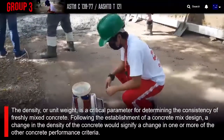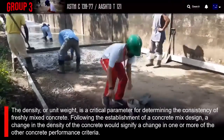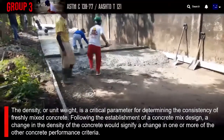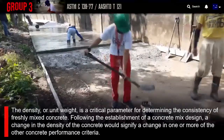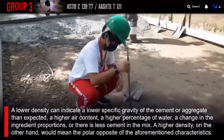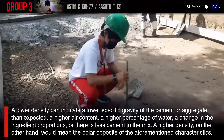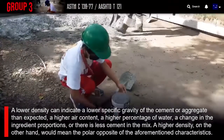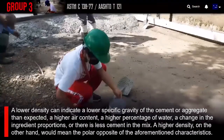As a conclusion, the density or unit weight is a critical parameter for determining the consistency of freshly mixed concrete. Following the establishment of a concrete mix design, a change in the density of the concrete would signify a change in one or more of the other concrete performance criteria. A lower density can indicate lower specific gravity of the cement or aggregate than expected, higher air content, higher percentage of water, change in the ingredient proportions, or less cement in the mix. A higher density, on the other hand, would mean the polar opposite of the aforementioned characteristics.